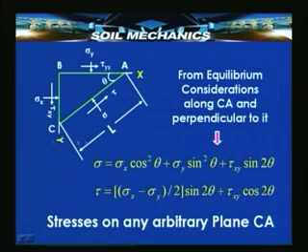If we have this scheme of stresses on a set of planes, in terms of the stresses on AB and BC, we can express the stress on CA from a very simple consideration that this element, and therefore that point P, must be in equilibrium. Suppose the length of AC is capital L; correspondingly BC will be L sin theta and AB will be L cos theta. Therefore, we can calculate the total forces on each of these planes and find the condition required for satisfying equilibrium of these forces.